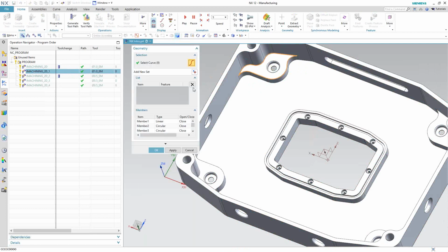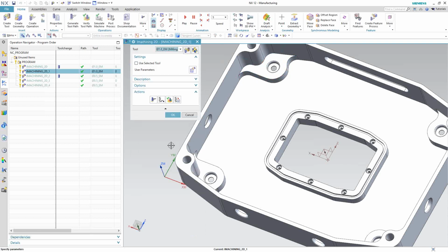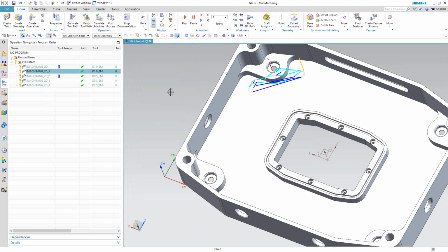Okay, and we'll go to our geometry. And I set edges 6 to 9 as open. So the red indicates that it's open. I'm telling SolidCAM that it can go across those lines and machine that option there.